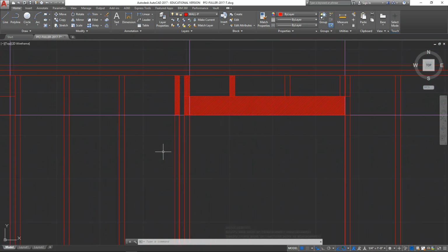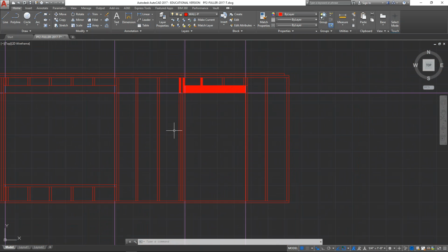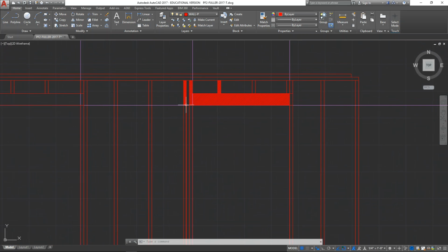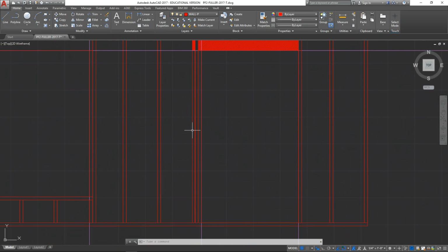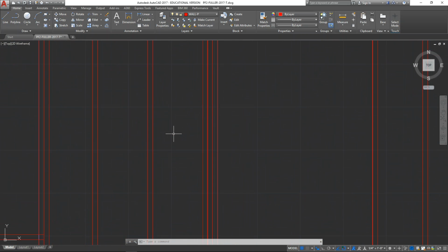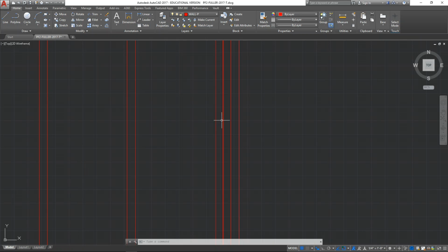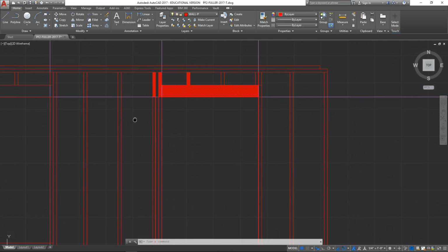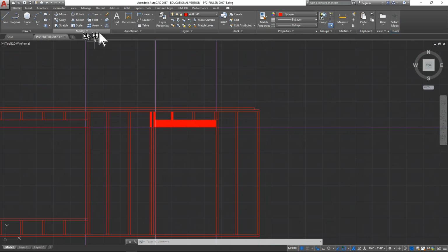Okay, well, if it won't lock on, like I said, it's not mandatory that you have that all perfect there. You do need that king stud going up and down the wall here. You have to have that. You don't necessarily have to move this stud over until it butts up on there, because all that will work, one and the same.